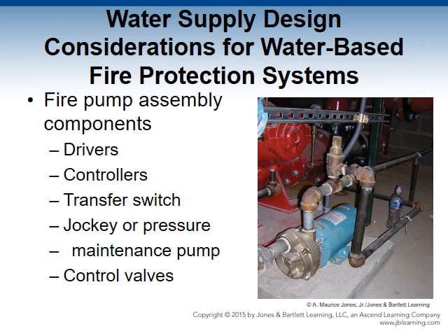Jockey or pressure maintenance pumps. They manage the pressure loss on wet pipe fire protection systems. They connect to an electric motor and operate by a pressure starter switch. They can boost and maintain the system pressure above the fire pump starting pressure settings. It is set up to monitor normal system pressure and change due to components such as fittings, pipe leak, or changes in temperature. If running frequently, this may be a sign of a significant leak or a problem with the pressure starter switch.